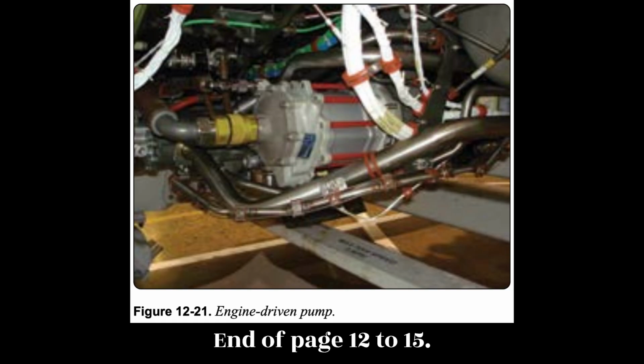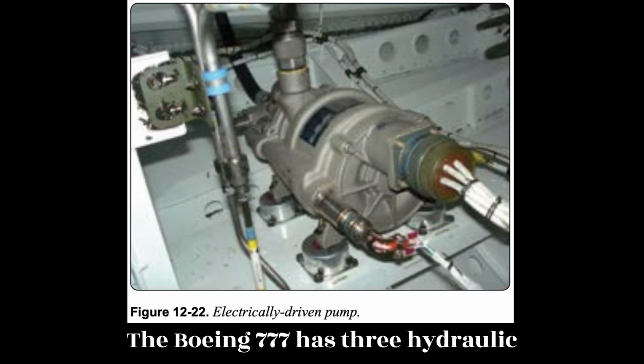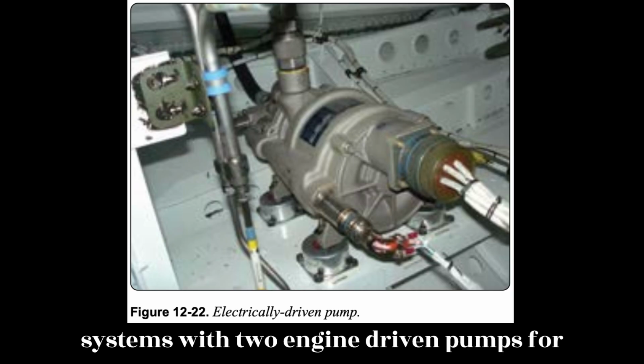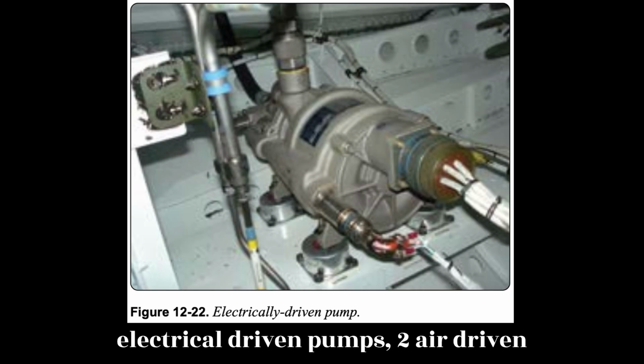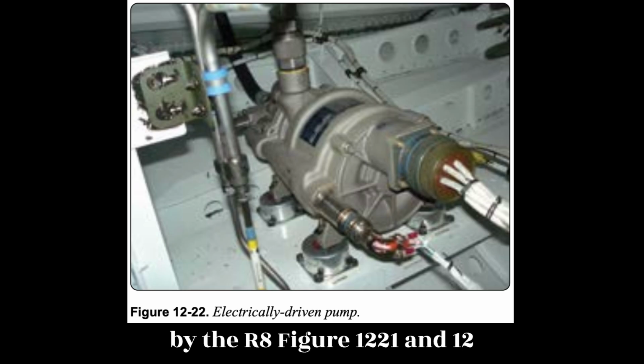End of page 12-15. The Boeing 777 has 3 hydraulic systems with 2 engine-driven pumps, 4 electrical-driven pumps, 2 air-driven pumps, and a hydraulic pump motor driven by the RAT. Figure 12-21 and 12-22.